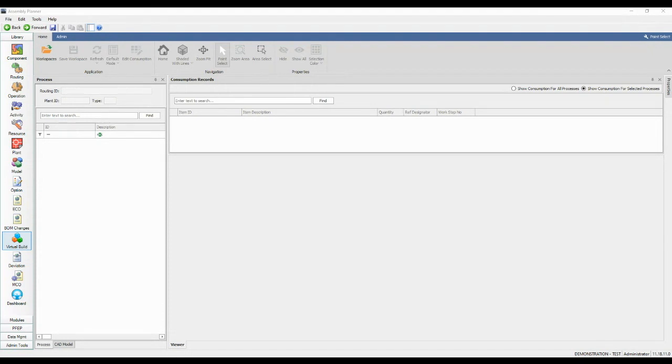And then we come down to converted CAD file format. This is the format of the converted CAD that we would like to use in conjunction with this workspace. Keyword being converted. Assembly Planner will accept many different native CAD formats, such as Creo Parametric, CATIA V5, SolidWorks, even neutral formats such as STEP.